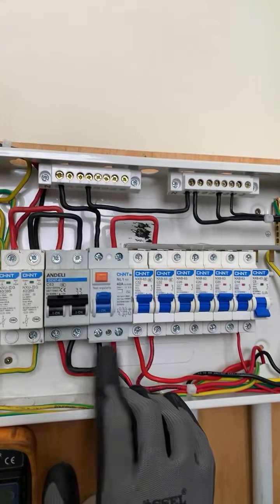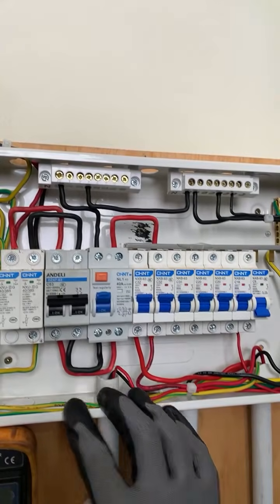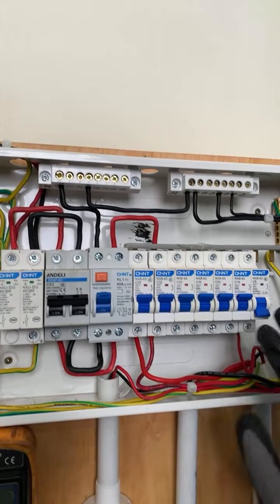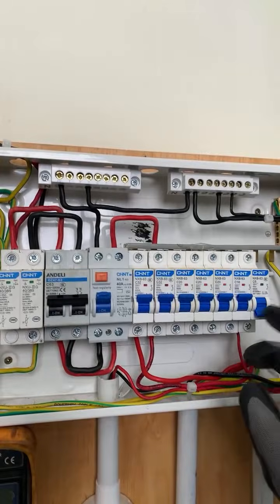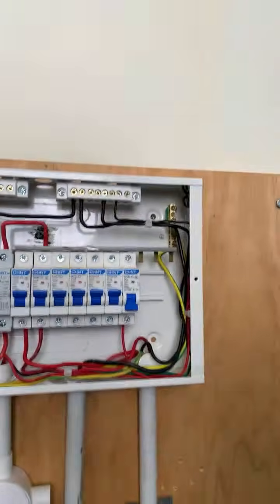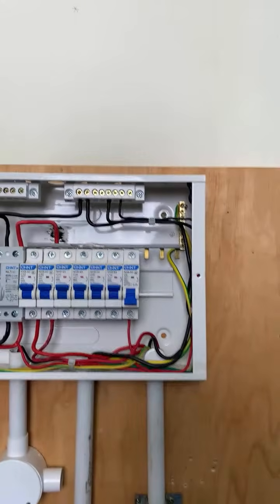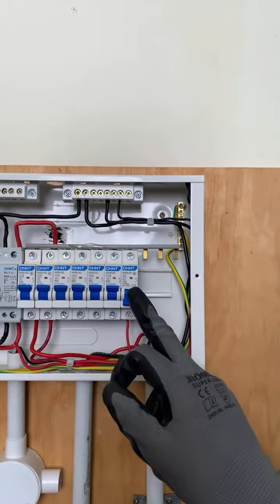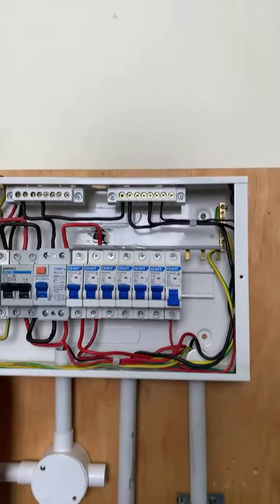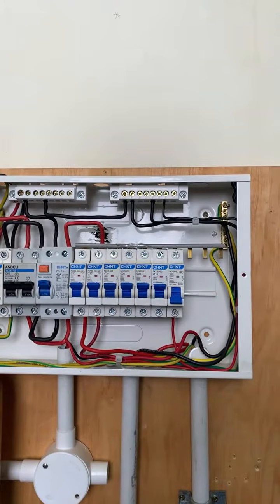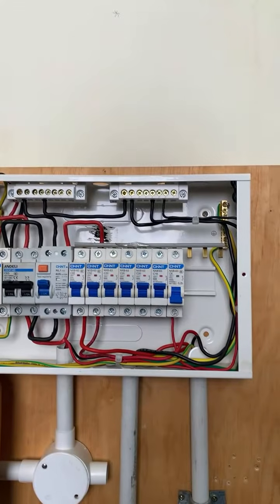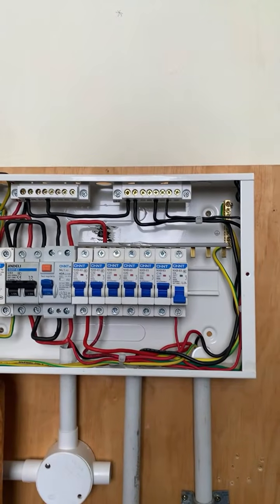So as an electrician, your first instinct should send you to the consumer unit, and that is where you find yourself here. And once you are here, you discover that there is an MCB that has tripped. And the reason why you will know that that is the MCB for lighting is because it is the smallest MCB. Assuming that we have a C16 for lighting as well, or a 5, that is okay, because in other rooms, there is a presence of light in them.